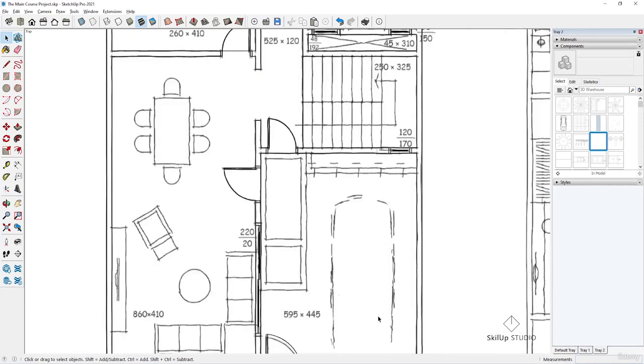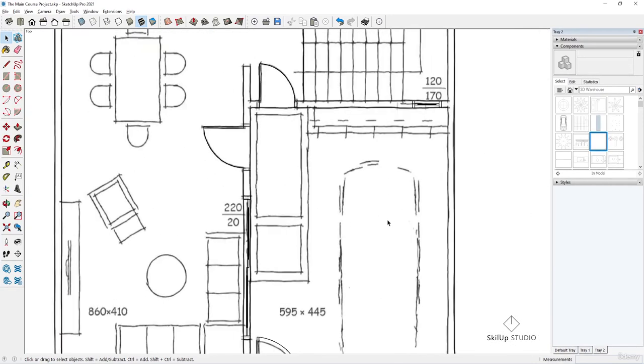After that, draw the garage landscape with the rectangle tool. Check the rectangle dimensions, it's 315 by 53. Make it 315, 53. Then delete this face and make these edges a group.